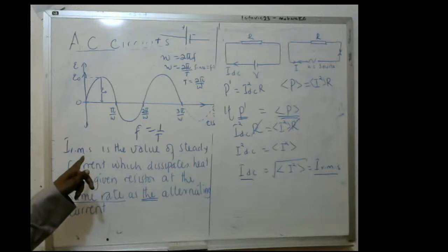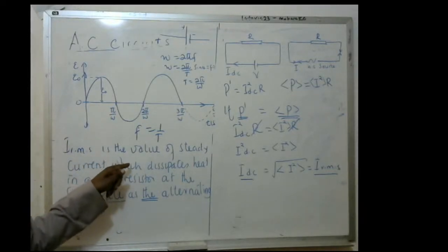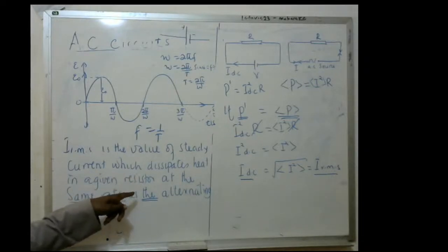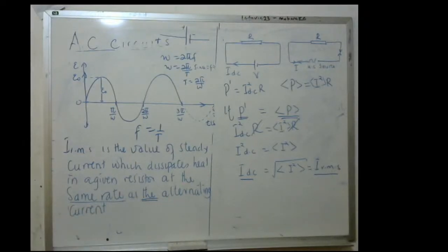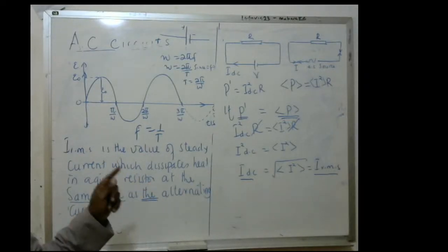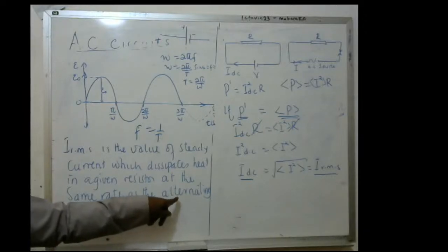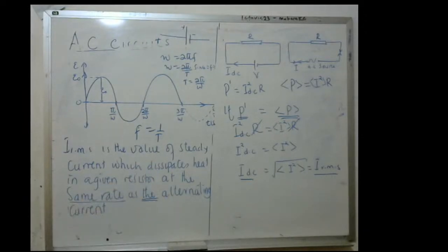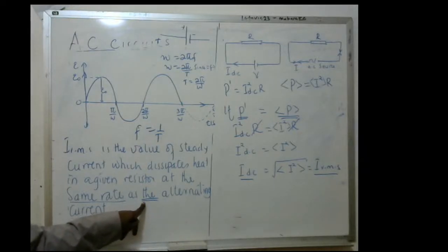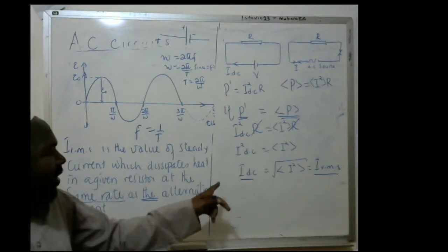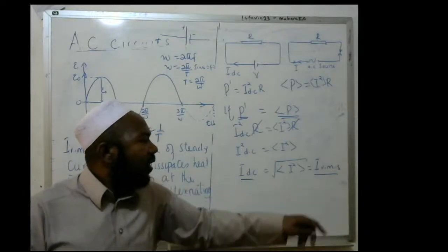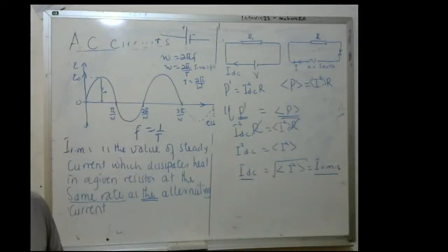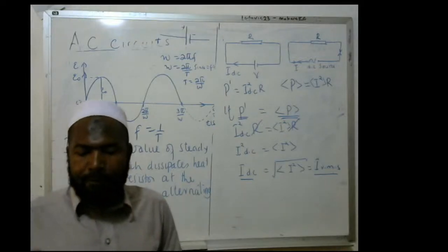Therefore, when you define the I RMS value of current as an alternating current, all those definitions will not count, because the nature of current we are dealing with should be specific to a value that dissipates the same power. And therefore, when you miss the article there, you'll be missing out. So that value of direct current that will dissipate the same power as the alternating current is what we call the I RMS value of current, the root mean square value of the alternating current.